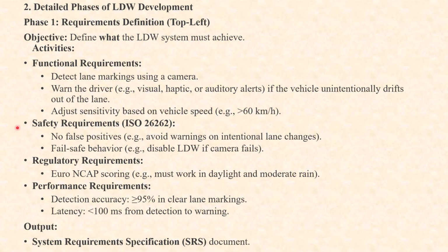Next is safety requirements. Safety requirements are based on ISO 26262. So the safety requirements are no false positives and fail safe behavior. For example, disable LDW if the camera fails, because LDW basically relies on the camera. Camera is the main sensor for LDW.